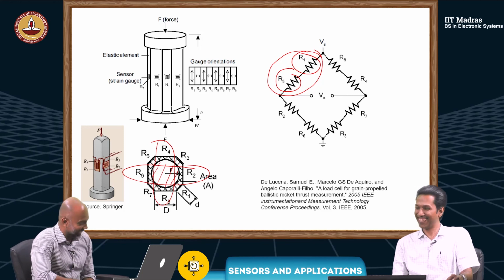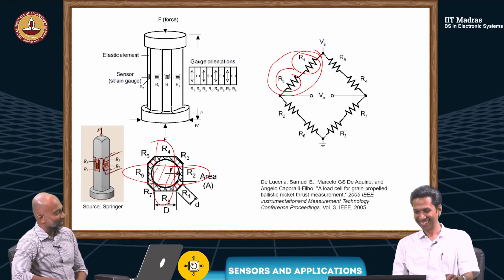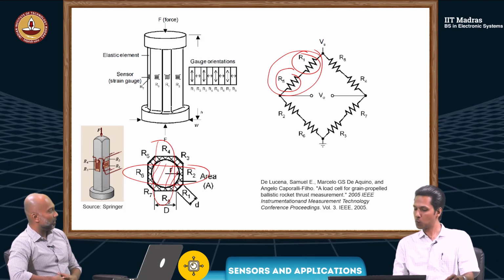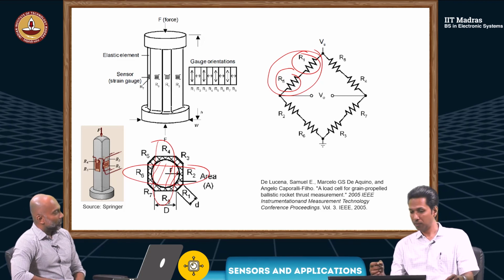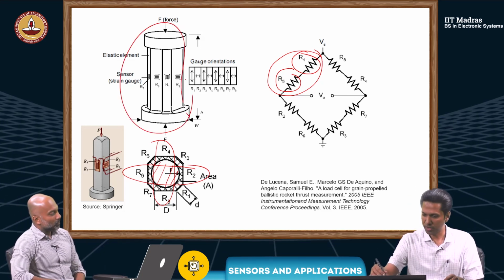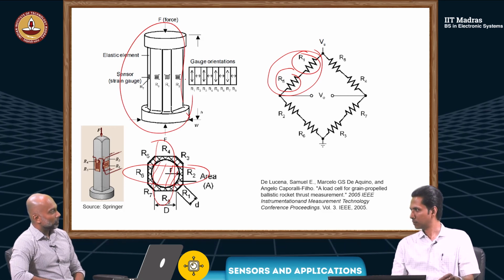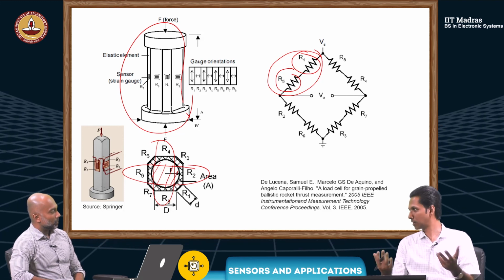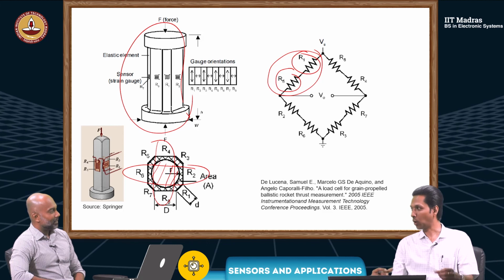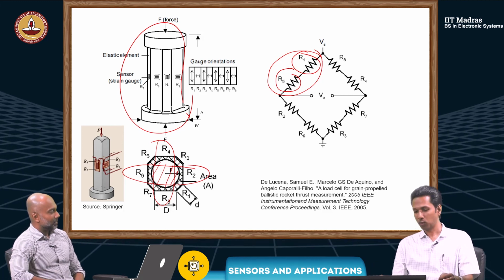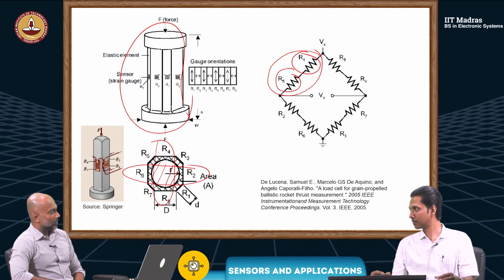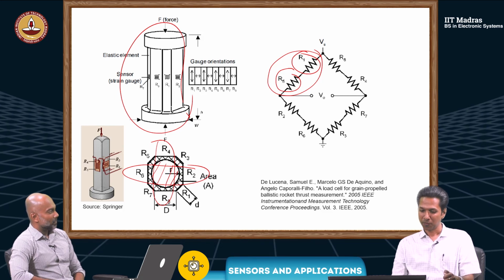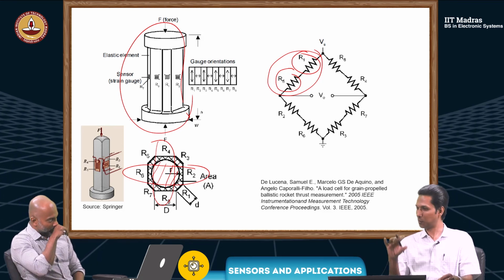I did not expect an application like this for strain gauges, but that also means you can use it in very harsh environments, I guess, in a lot of ways. Yeah. That way, these kinds of structures, the load cells, are quite rugged. Even if it is dropped from your hand, nothing is going to happen. This is made of very strong material, or stainless steel, which can handle tons of mass if required. Yes. And the strain gauge is just an attachment to that to sense this strain.